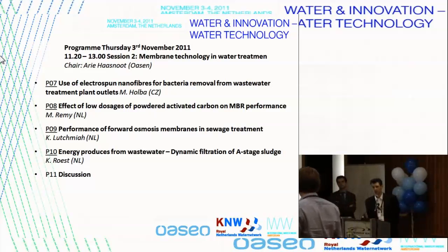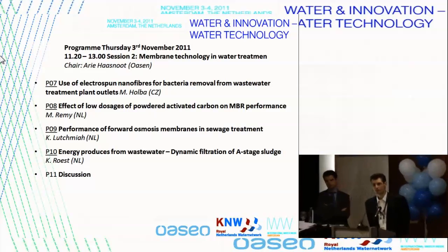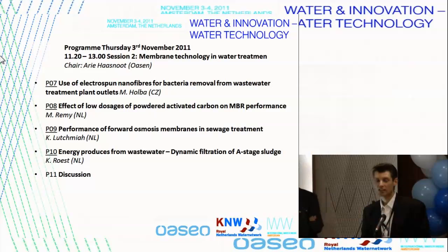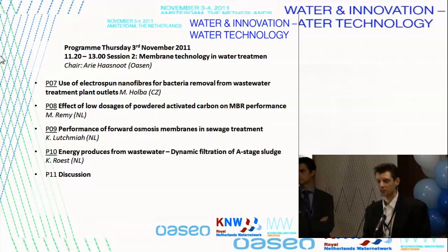So if you have a concentrated organics stream which goes to the digester, then in the digester you will convert the organics to biogas, but the nutrients stay in the effluent. But it's still a concentrated stream, so it could be very beneficial for harvesting the nutrients. And there are some technologies for this, of course, like struvite precipitation and other technologies, which are also still very often not applied because of the economic factors. So it's still more expensive than producing nutrients in conventional ways.